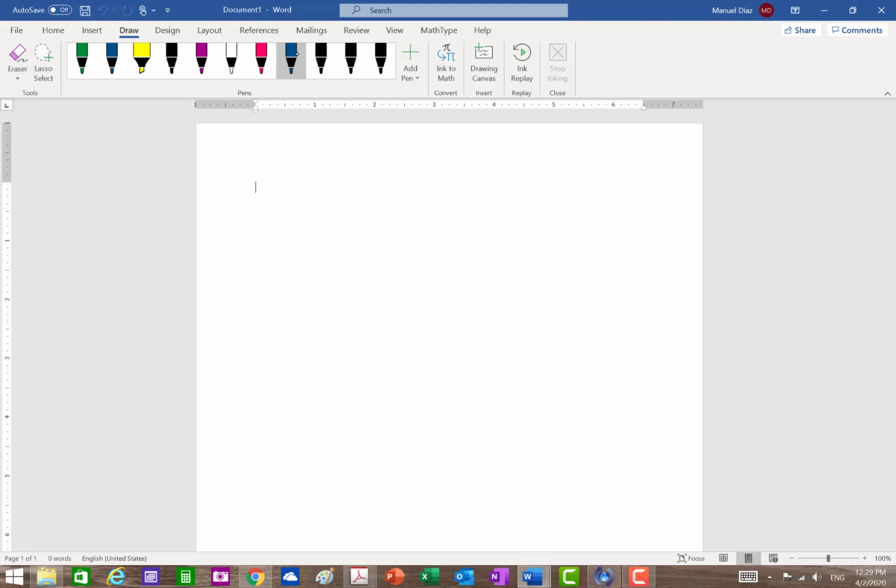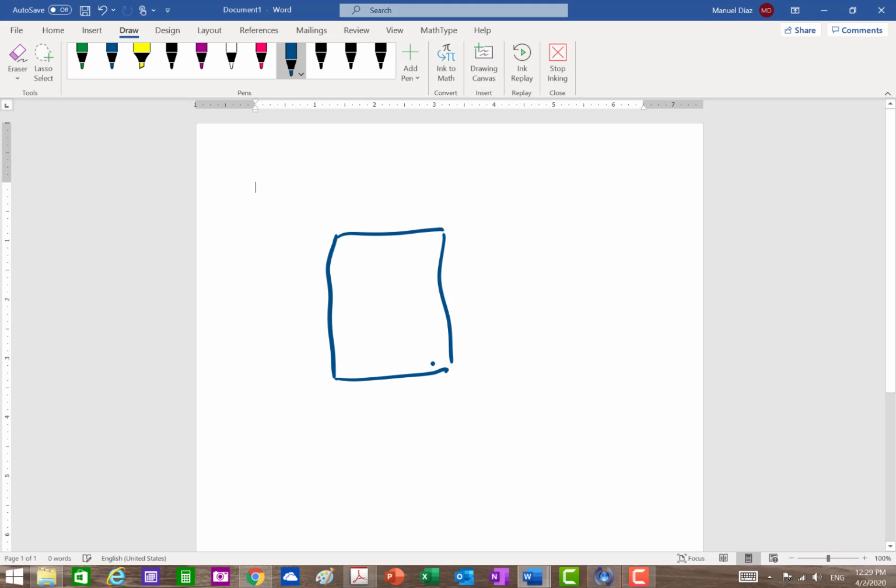Now here is the part that I usually fail to do. So you're going to have your beam, and you're going to have, let's say, 3 bars in compression. So you're going to have an element here, your stirrup, but it's closed, and it has to have these elements here, completely closed.